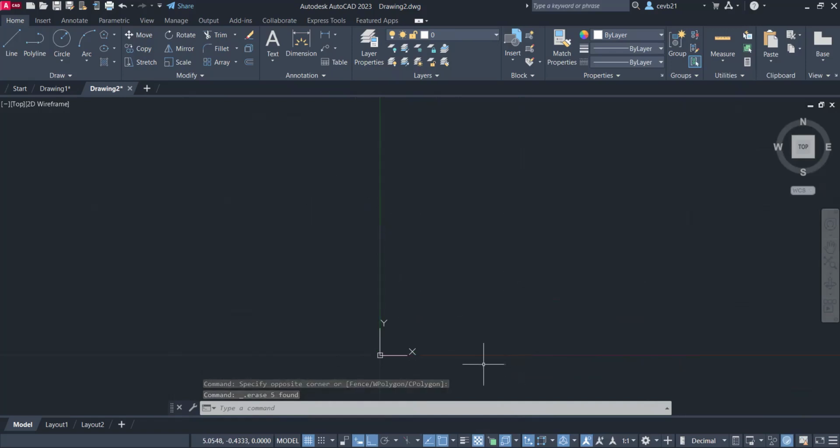So for polar coordinates, the format is the shift at, or the at sign, the distance, and then the angle. Like what I told you last time, our reference would always be from here to here. From here to here, the angle will be 0. From here going up to the green line is 90 degrees, and from the center to the left side would be 180 degrees, and from the origin to the down side of the reference line would be 270.